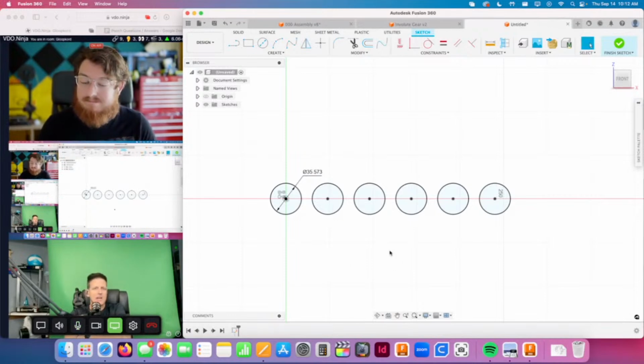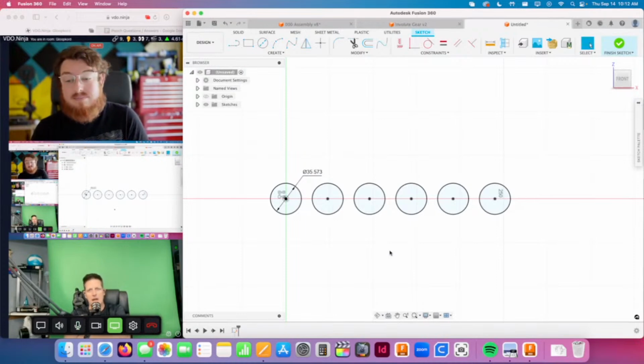Thank you for the discussion on that, because like I said, there's no one right or wrong way. There's a million different ways to get it. I'm used to sketching a hole, but the Hole tool inside of Fusion itself is more powerful in certain ways for manipulating things when it comes to threading and other stuff as well. So you don't necessarily have to manually model each of these holes. Sometimes giving context that it is an actual hole is useful as well, which is a whole other thing. Pun intended.